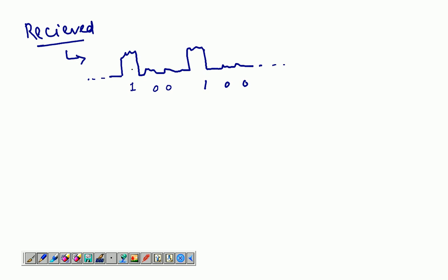So how do you translate this into a perfect signal that was transmitted? The signal that was transmitted was something like this. How do you convert this back into the signal? So the easiest way to do this is to repeat the process of quantization. If you repeat quantization, what quantization does is it cuts off this noise and it keeps the digital symbol representing 1, and then it cuts off this noise, this and this, right?